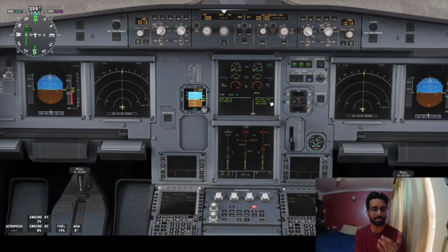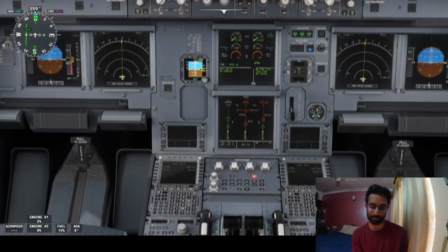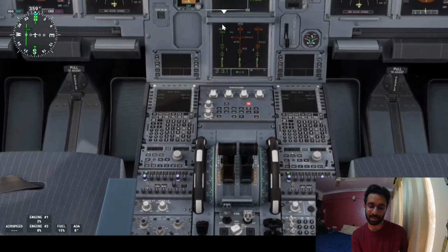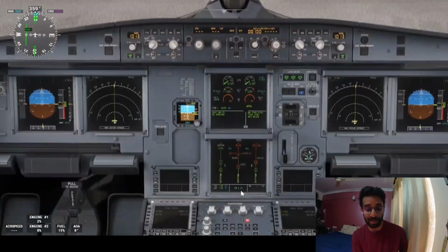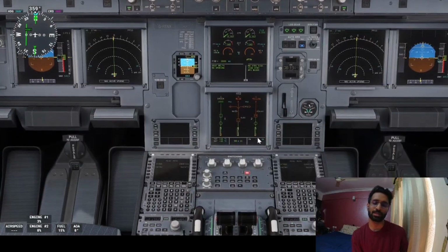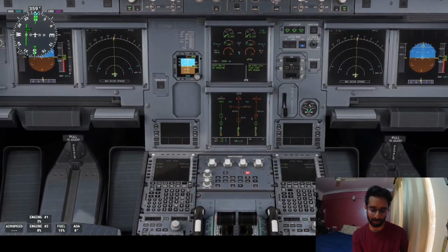The third condition says the parking brake is released and the nose wheel steering is not in towing position. Here the nose wheel steering is in towing position. So even though 500 psi is there between green and yellow, because the nose wheel steering is in towing position, the PTU is inhibited. Which is why engine 1 started, EDP kicked in, 3000 psi, a 500 psi pressure difference is there, but the PTU is not working. PTU is inhibited now.